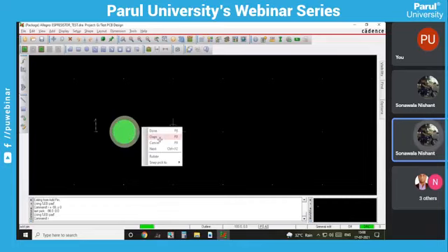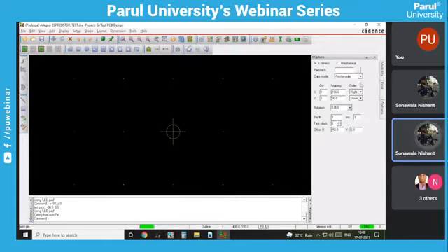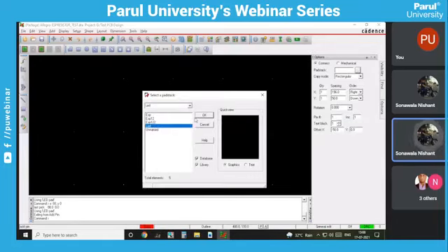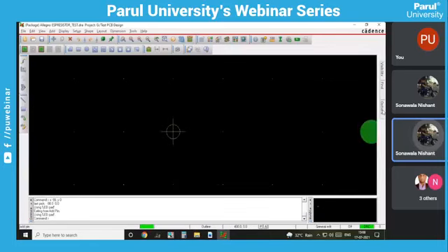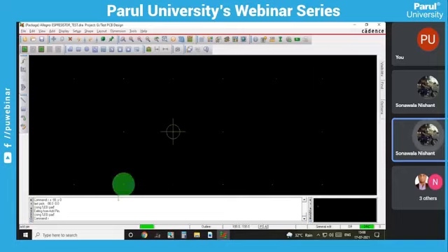Why? Because we have done only one part selection. So what we have to do, first of all we have to go to select a pin, pad stack, choose our pad, and then mention the quantity as 2 pins are required. So mention the quantity as 2. Now again write x minus 98 comma y 0 and enter.